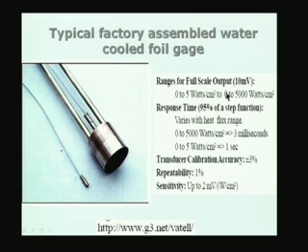There are several ranges available. The gauges are made in different ranges, 0 to 5 watts per square centimeter up to 0 to 5000 watts per square centimeter. It is a very high heat flux. In the case of high heat flux gauges, you may have to have good cooling arrangement. For very low heat flux gauges, cooling may not be necessary, or air cooling may be sufficient.